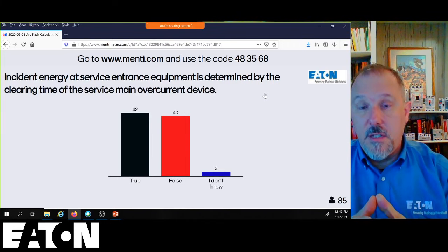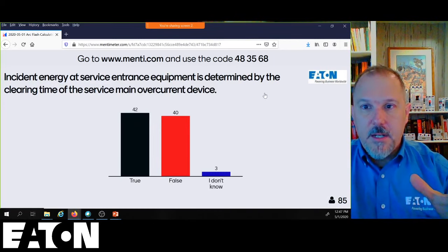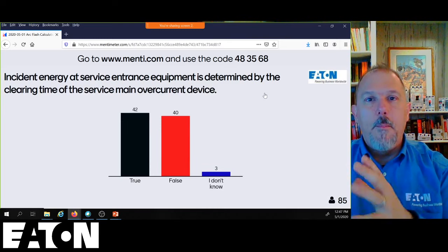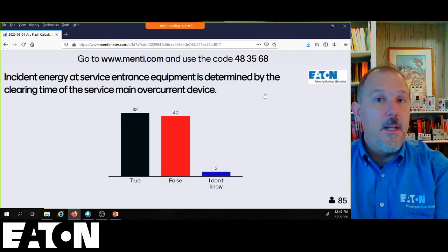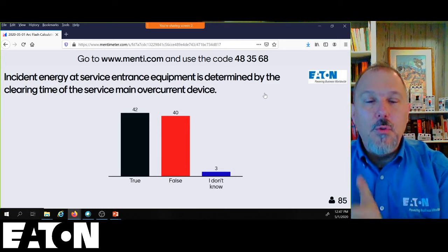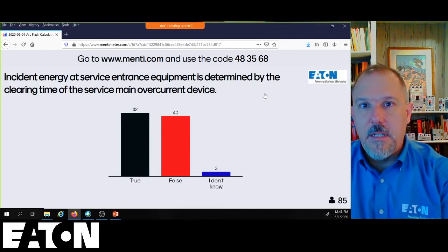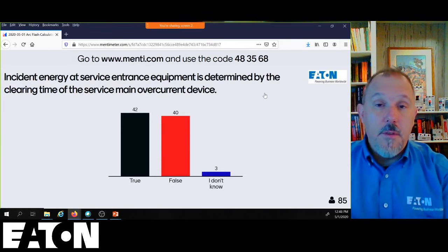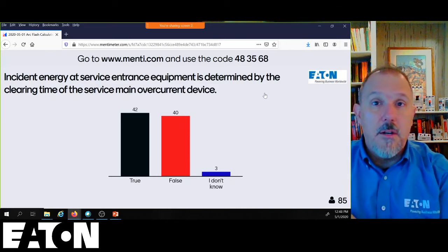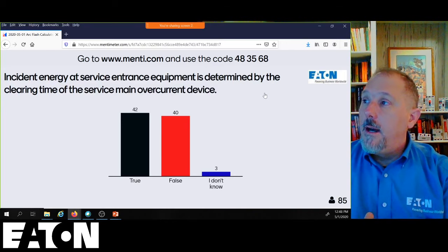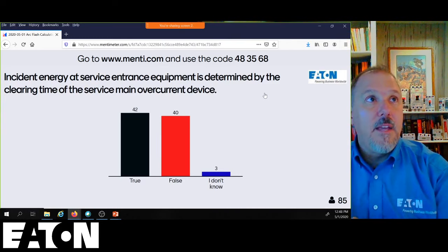Now, if you've designed your system carefully, your service equipment is hopefully a breaker in a box or a fusible disconnect switch, and then your actual panel board is not a service panel board, it's a feeder panel board, a downstream panel board from that service equipment. It's not service equipment, and now you can take advantage of the arc reduction technologies or the capabilities of the overcurrent device upstream. I've got pictures of this, and we're going to talk about this in more detail. My chips are all in the true basket on this one and not in the false basket. I base that on IEEE 1584 and the guidance that they give you.